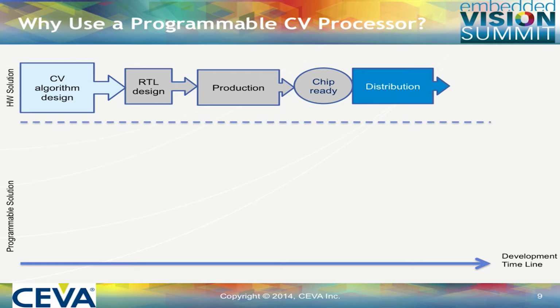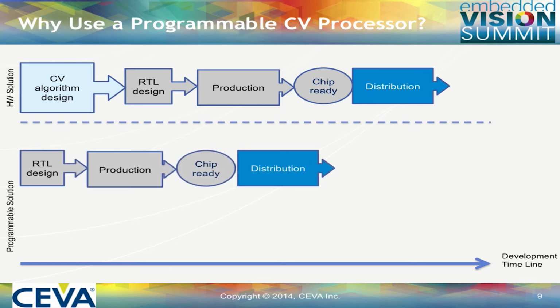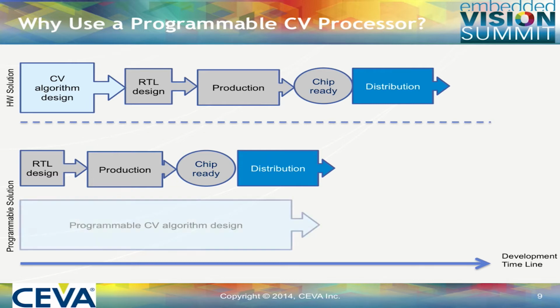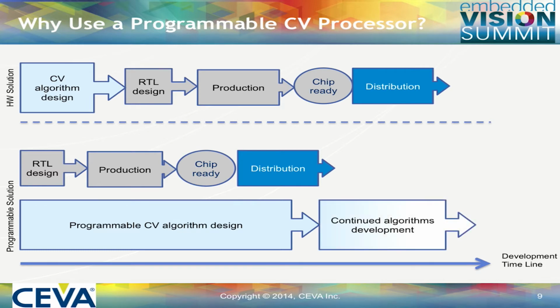If we go with software based on a DSP, you can start the RTL design, production, and go to distribution without even completing the algorithm. You can design your algorithm well through the distribution stage, and even after the product is already in the hand of the user, you can continue improving, even writing totally new applications that you did not even think about when you started this project, because you're on a programmable option.